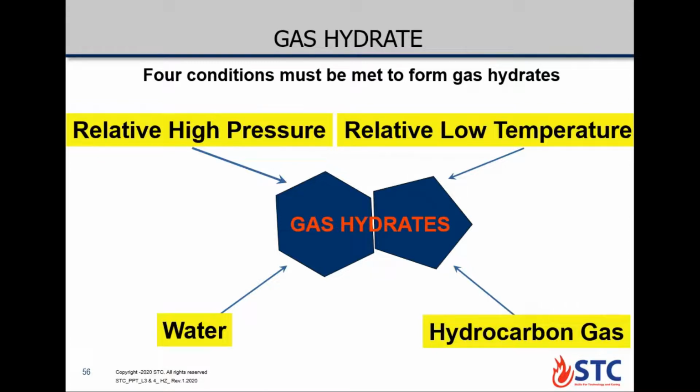You have high pressure, you have low temperature, and water vapor, plus the return contains gas, so you will form hydrates through the choke or downstream of the choke, usually downstream, because there is variation in pressure and temperature downstream. So it will block and build up pressure above and stop the killing operation.